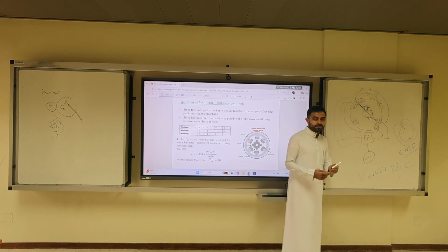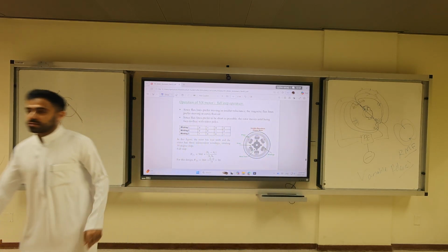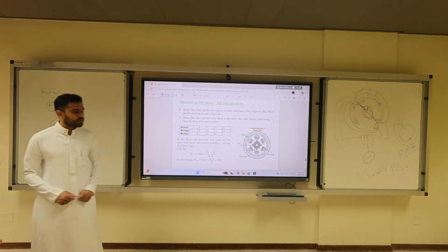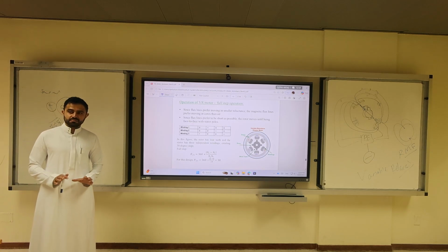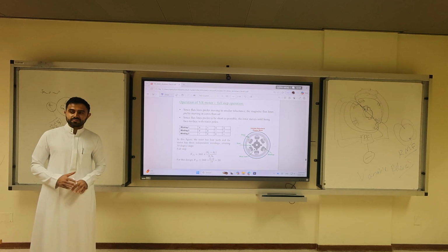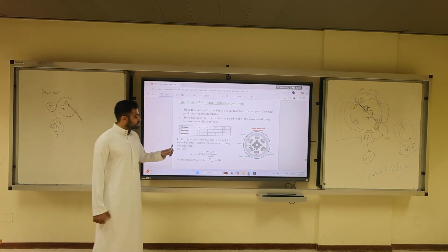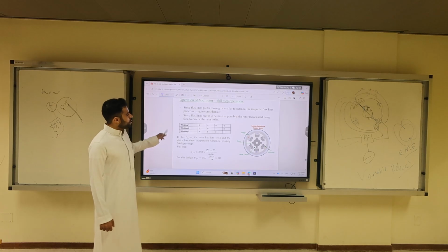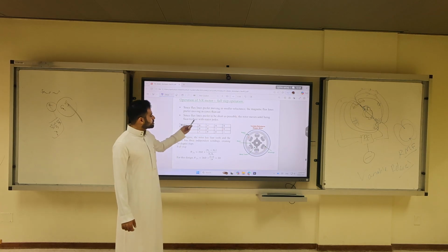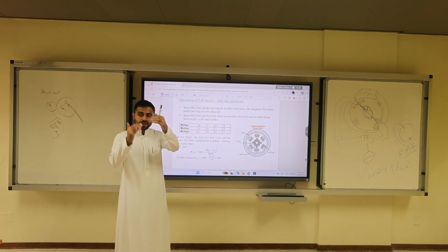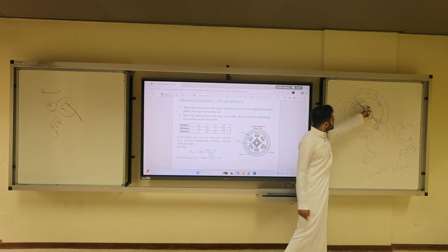Get it? Doctor, what about the 4 poles? I'll explain. 4 poles means you will have power electronics that's more advanced. But let's think of it simply. Flux lines prefer to be as short as possible. The rotor moves until being face to face with the stator pole. They have to be face to face.